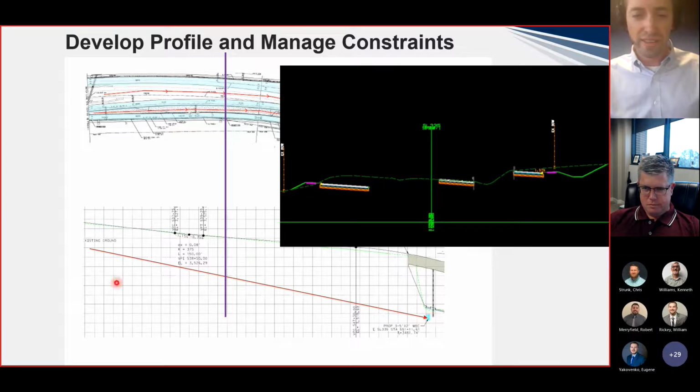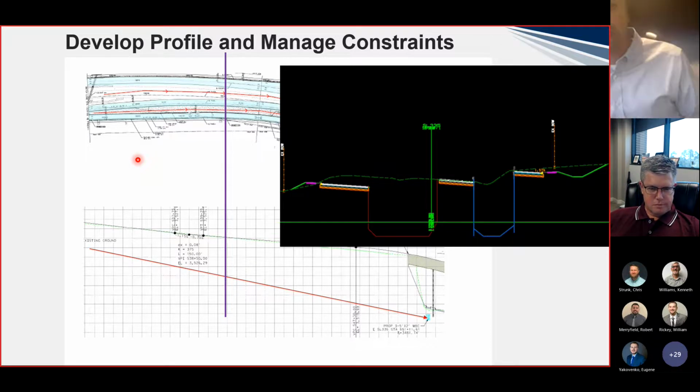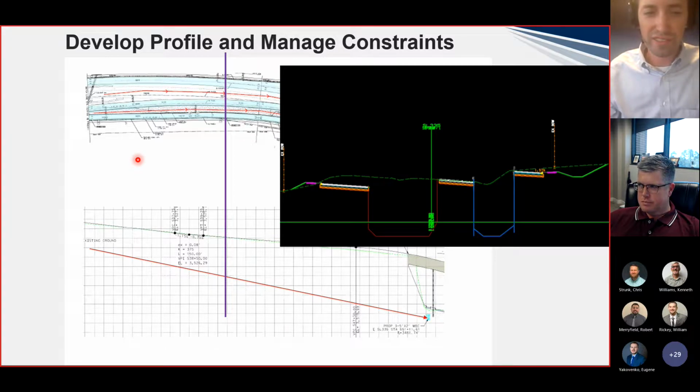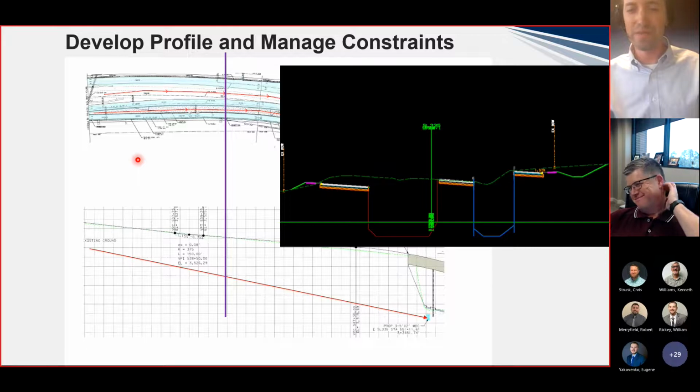So now looking at what that is going to look like in our cross-section view for this area and this area, because those are the two, that's this ditch and this ditch. We get something like this, which from a drainage perspective, if the roadway came and said, hey, we want to put 30-foot retaining walls right next to our road, from my perspective, this works. I know I'd get a call from Gary in a couple of hours, but I have no problem with it. But we know this isn't the most feasible design.